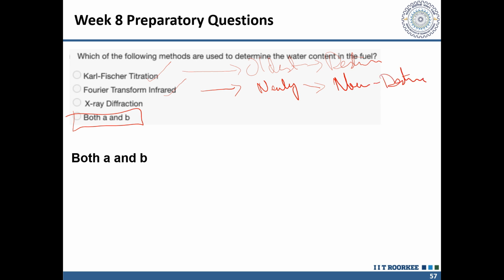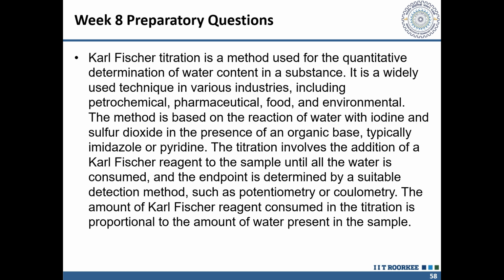So only a drop of oil will be used to analyze this. So FTIR is now being more applied nowadays due to its non-destructive nature and requirement of very little oil. Karl Fischer titration is a quantitative method to determine the water content in oil and is a widely used technique in petrochemical, pharmaceutical, and environmental studies, and it's based on the reaction of water with iodine and sulfur dioxide.